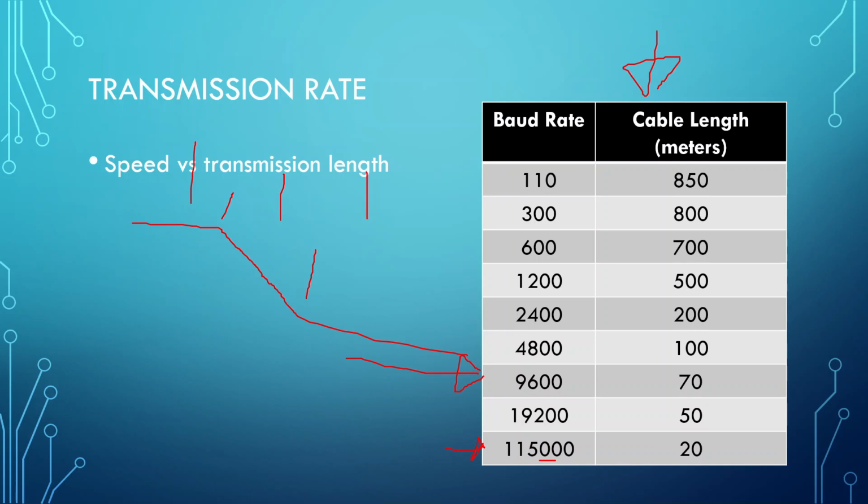Well, according to that, I would have to use a 600 baud rate. Can I bump that up a little bit? As long as both devices support a specialized baud rate, there's nothing saying that you couldn't try bumping that up until you start seeing errors, and then backing that off a little bit. You could do that, as long as both devices understand how fast you're communicating. Perfect.